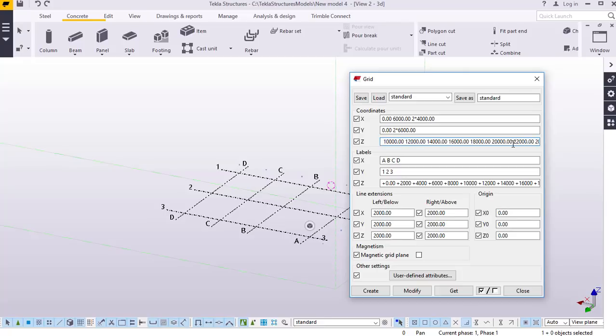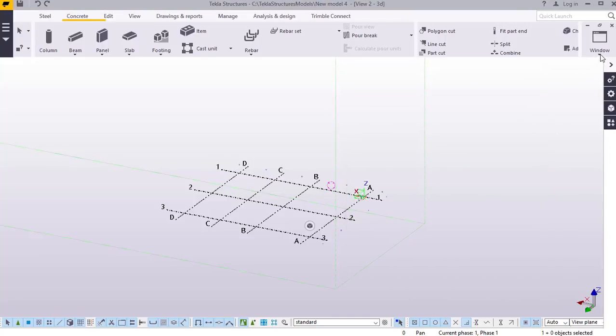Let me just scroll to the last dimension. You'll see it there. It's 40 meters. Similar to this, just go to the utmost height. You'll be able to see it is 40 meters. And remember, at the moment you feed your dimensions here, just copy paste and prefix them with a plus sign, and that is enough. I'll switch back to my elevation A. Now I'll close this, then come to Windows here and pick my elevation A as grid A.